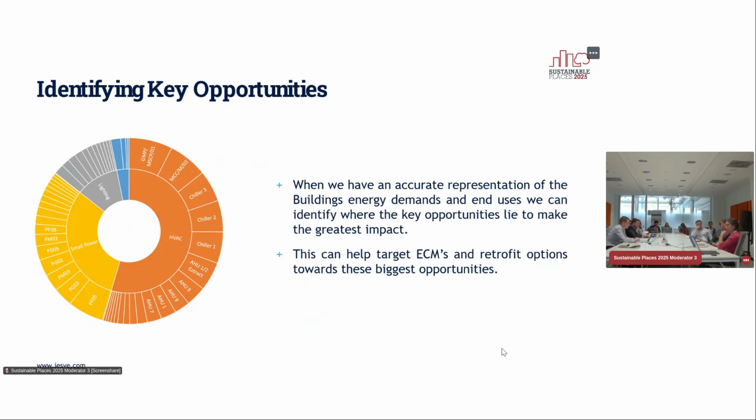So we could then use it to go into a very detailed breakdown of the energy demands of those buildings. There's a feature in the virtual environment software called sub-metering, and that helps look at the energy demand and really understand where the demand is and where the greatest opportunities to save energy are. That in turn helps us identify and explore the energy conservation measures that are most likely impactful in reducing the demands, right?